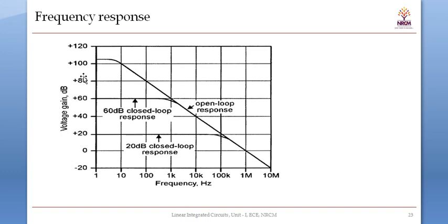So here the manner in which the gain of op-amp changes with the variation in frequency is known as magnitude plot, and the manner in which the phase angle changes with the frequency is known as phase angle plot. So the rate of change of gain as well as rate of change of phase shift can be changed by using specific components